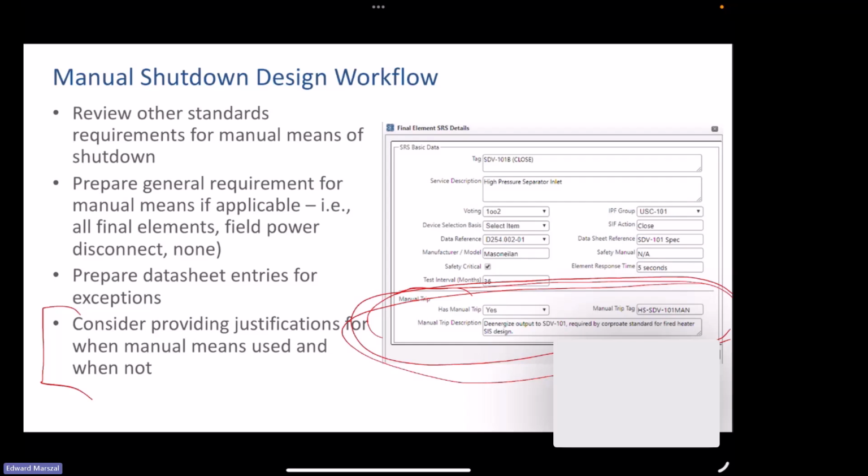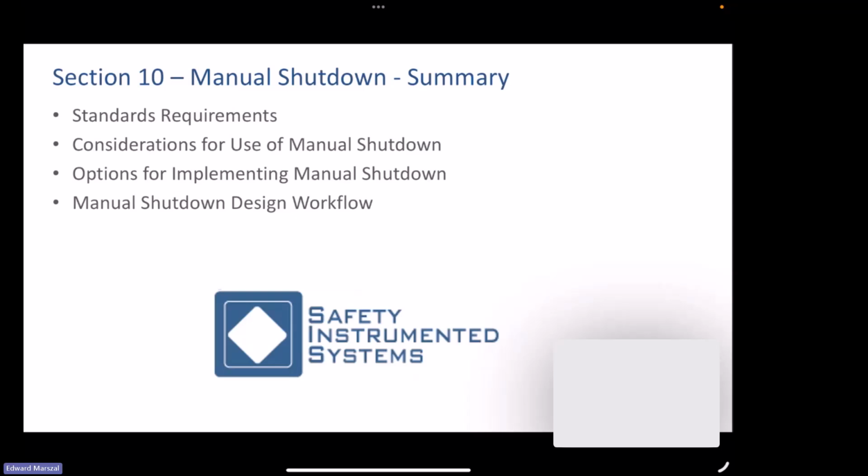So that's our workflow for designing manual shutdown. So in summary, wrapping things up, in this webinar, we talked about the standards requirements for manual shutdowns, and the standards requirements were pretty brief. They said you need to document what you're doing for manual shutdowns, and you need to provide a manual shutdown for every final element that's independent of the SIS logic solver.